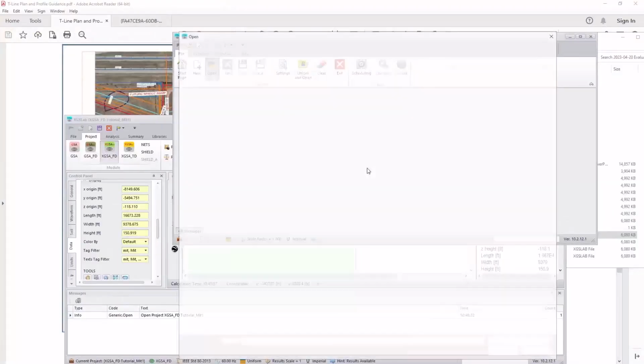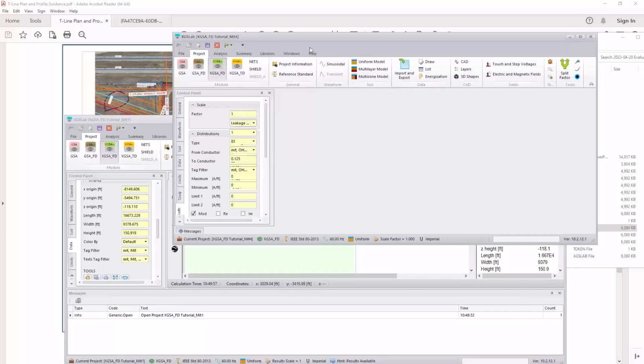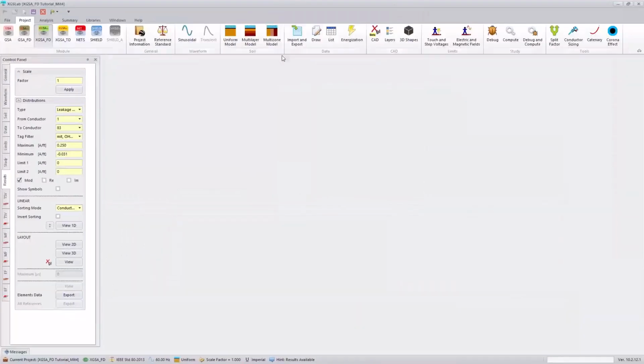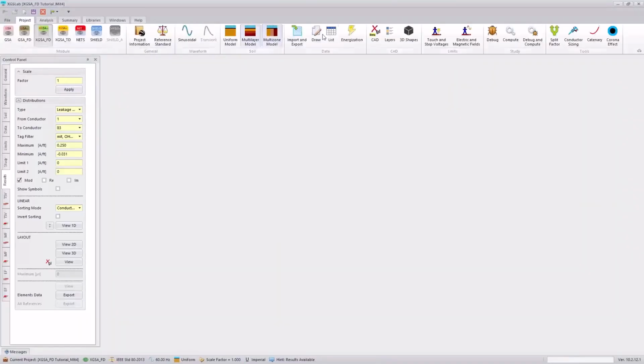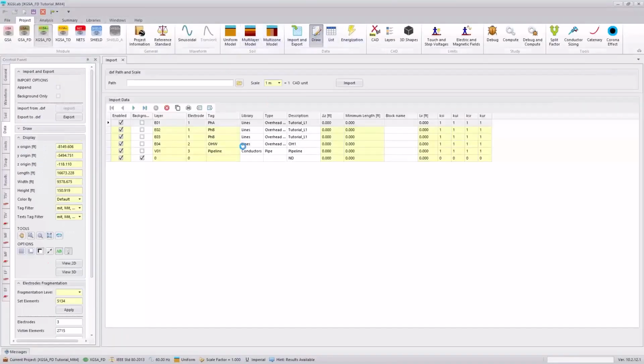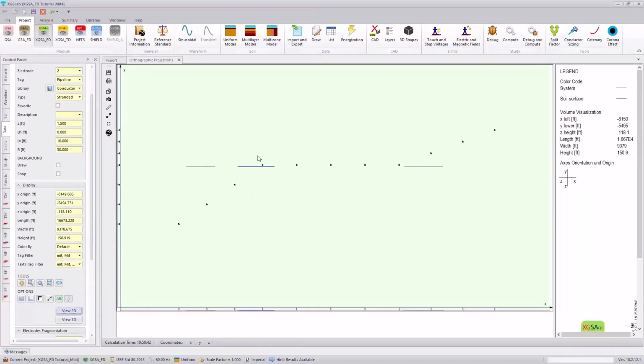So I'll open up mitigation 4, for instance. And all I do is I actually just put in what I think would be an excessive amount of mitigation, and it's easier to step back from that. So I want to show in my draw view, if I filter my view to just that mitigation, now we just have this one section of ground conductor.